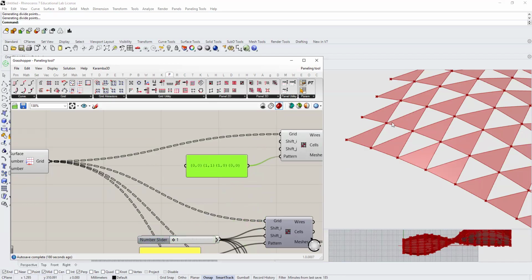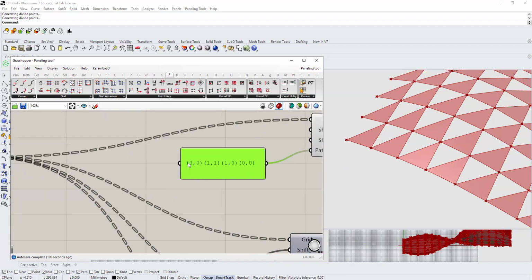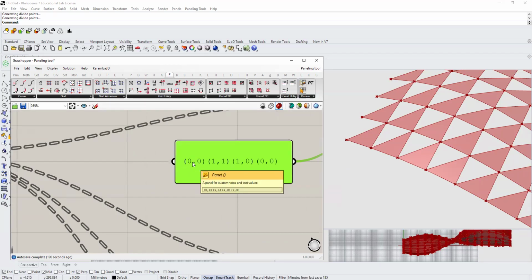If you want to create this rectangular pattern, you know that you should start from a point, continue to the next, and get back to the original point. So I will start by keying the pattern into parentheses, disregarding the z value. I said this is 0, 0, and then I want to connect it to 1, 1, then to 1, 0, because along the first direction this coordinate is 1, and along the second direction it is 0.